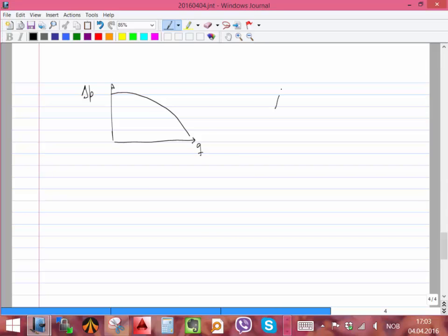Remember that we have, for example, a space like that, and we have fluid coming with a certain velocity. If we put gas, then the velocity does something else. The gas accumulates here and then restricts the passage of the liquid. It does a lot of bad things to our impeller, to our diffuser, to the whole system. So then maybe we won't be able to get this curve, but we will get, like with the viscosity, something completely different.